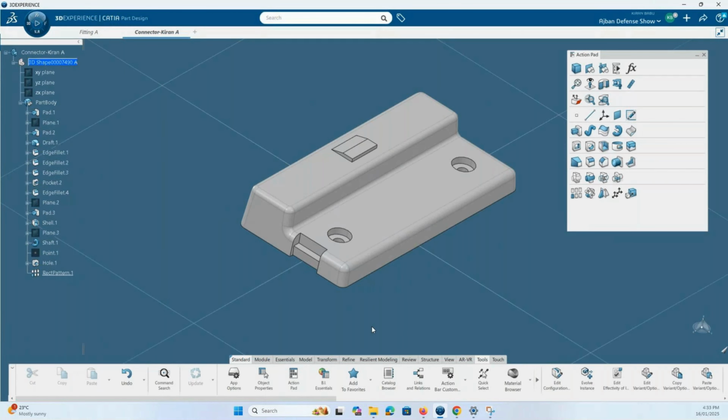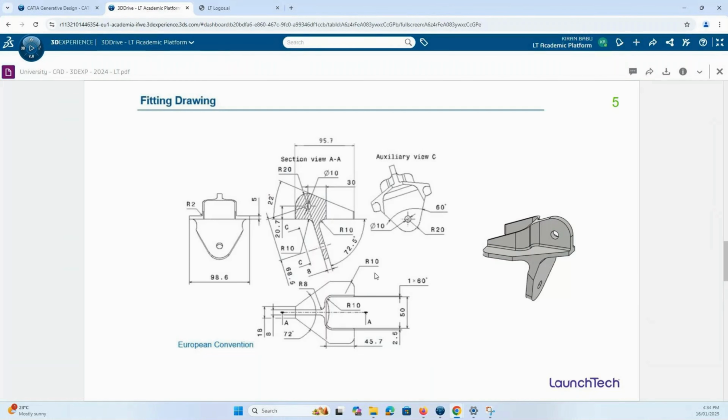Okay, so the way I have been doing it, and I've been trained over the years, is, like I told you, when you're trying to develop a solid model, you start with creating the base feature. As a designer, it's very important to understand how you look at a drawing. You have to go through multiple drawings and go from 2D to 3D conversions. Basically, take a 2D sketch and develop a 3D model out of it, to understand what would be the base 3D model.